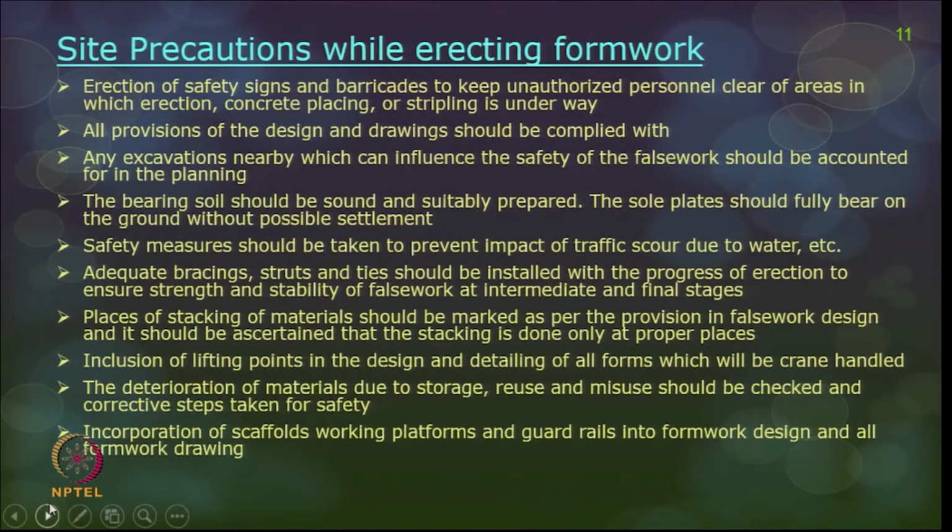Inclusion of lifting points in the design for lifting the formwork panels should be clearly indicated, and the details of the formworks should also be indicated when they are crane handled. The deterioration of materials due to storage, reuse, or maybe misuse should be checked, and corrective measures should be taken for safety precautions before you are using the formwork.